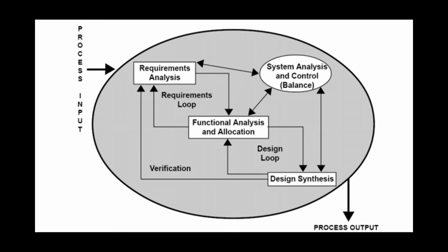In a railway, the operating mode scenarios impact the functional scenarios. You have got emergency modes, degraded modes, normal operation modes. So those modes impact how a system will function, how a tunnel ventilation system will function, how it will update itself, how it will operate itself, or where an operator will need to intervene. So it's an iterative process of identifying functional scenarios and functional elements, and then allocating them into, if you look at the design synthesis, design elements.